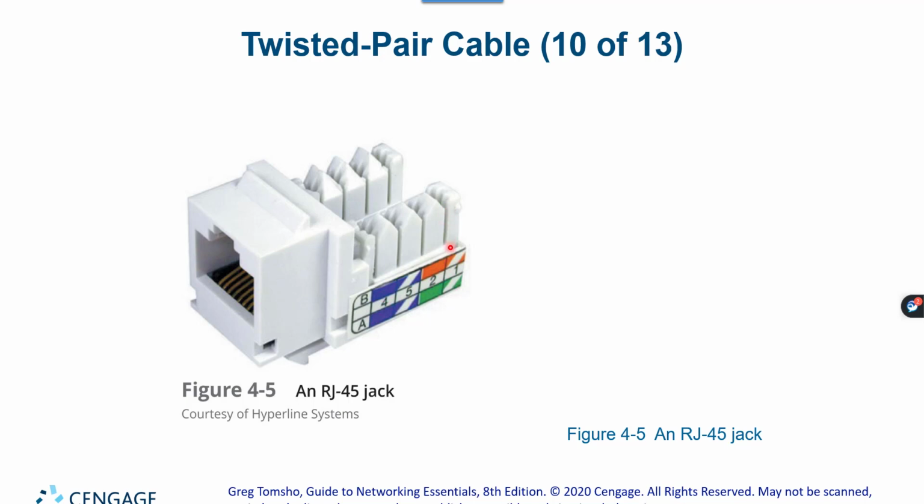These slots have metal connectors in there, and when you push the wire down, it bites into them and holds them. So a technician is going to come with a special tool called a punch down tool and push the wires into these slots inside of the wall.